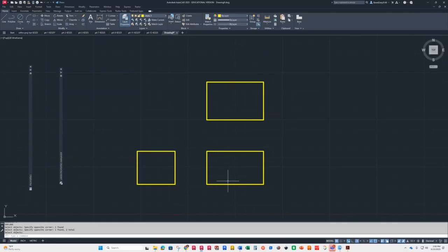All right. So now we could draw our shape here on the front. There's these pieces over here, which I just goofed up. So offset 0.25, enter. There we go. All right, and then looks like you have to come in an inch, so you're going to offset an inch, like that.